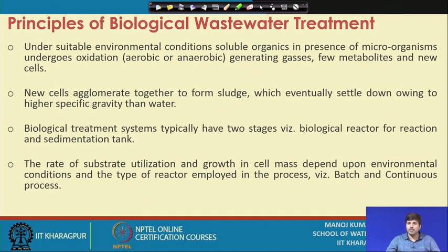the previous week. In the case of sedimentation or grit removal, the horizontal flow velocity is to be reduced in order to allow settling, and that is why it becomes an important step of the biological treatment system. So, the biological treatment systems typically have two distinct stages. One is the biological reactor, where the different reactions take place. Different reactions means including oxidation, the formation of new cellular mass, formation of gases, the